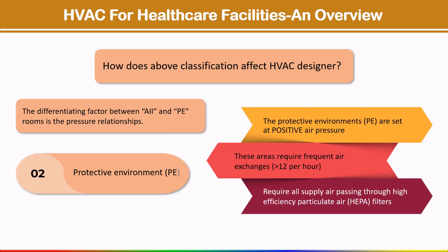Where can we use this type of HEPA filter? Some applications are clean rooms like hospitals, pharmacies or medical facilities. The HEPA filter is used for removing particles 0.3 micron in size. See how small a particle you can remove with this filter. It is used on the supply air distribution of the protective rooms. The HEPA filter removes particulates such as microorganisms from the air.